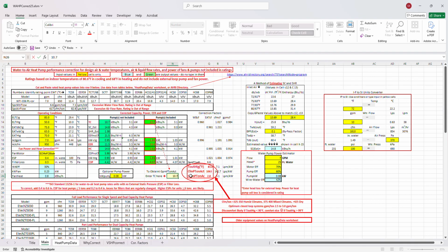It's going to go down a little bit below that. So we're still way over there. So let's drop this down to values for a machine that's a little bit less than that. All right, so it's dropped it down to 2.5 GPM per ton and 350 CFM. So we're going to adjust this back to 9.9, and let's see what happens here.